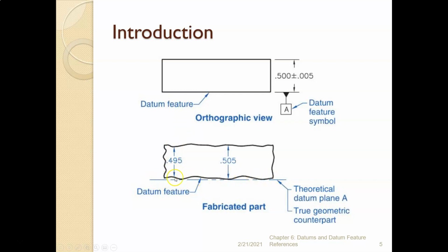Well, we can't really use a bumpy surface as a datum because a datum needs to be a theoretically perfectly flat plane. So we use a theoretical datum plane A that the part is going to rest on. And notice it rests right there and right there and right there. So it's sitting stably on theoretical datum plane A.